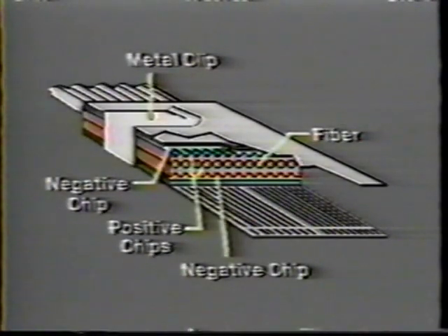A simple butt splice is completed out in the field by using two negative chips, which mate with the positive chips, and then injecting an index matching gel between the chips to avoid any signal loss. Small metal clips hold the entire assembly together. This arrangement provides the precise end-to-end fiber alignment necessary for good optical connections.